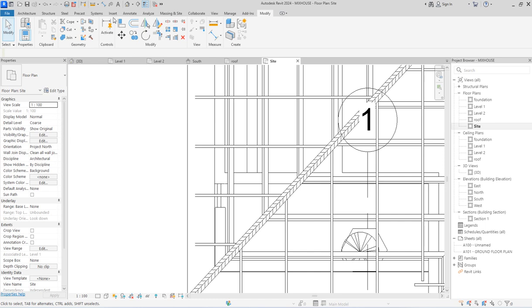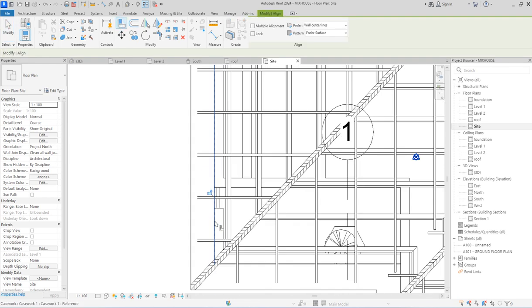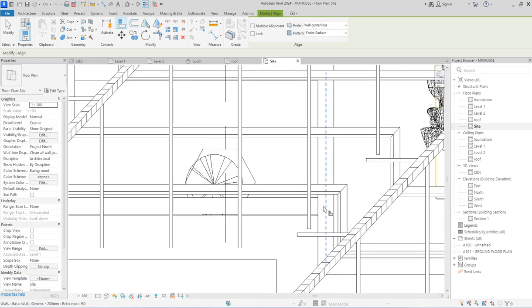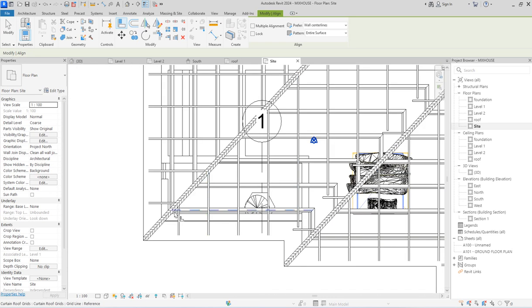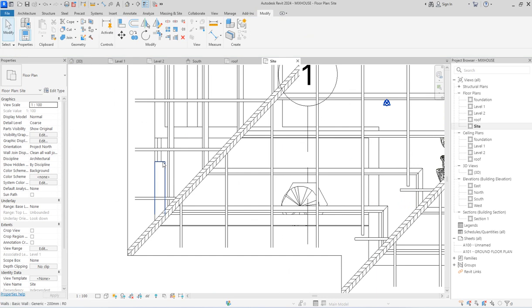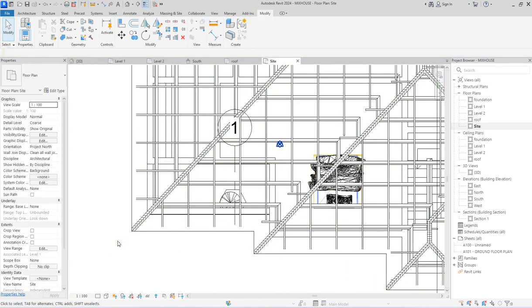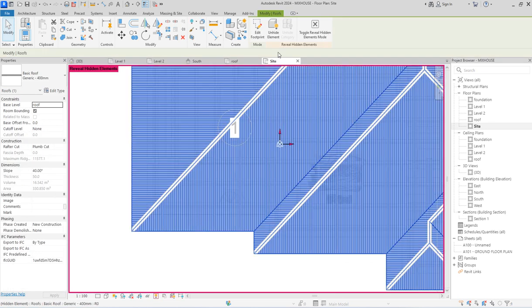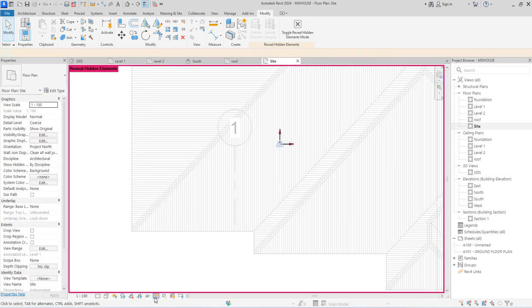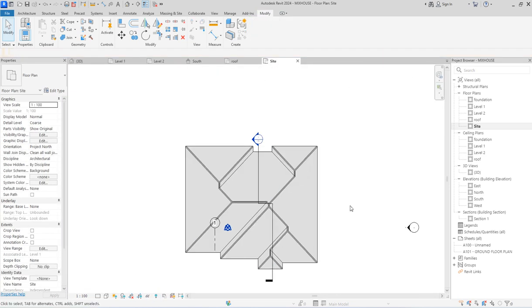This is what we have done. I want to align it to the wall so that you have the same level. This one does not have the same level with anything, so it can stay wherever it is. So what we do here, you unhide the hidden element by clicking this one, then say unhide the element. You come back to normal, then you close this up completely. That is what we've done here.